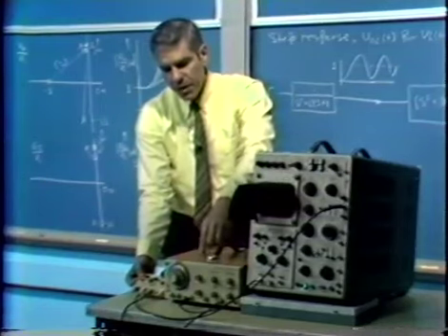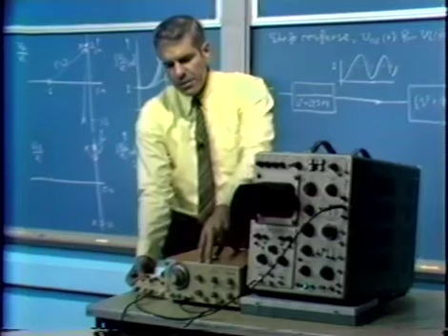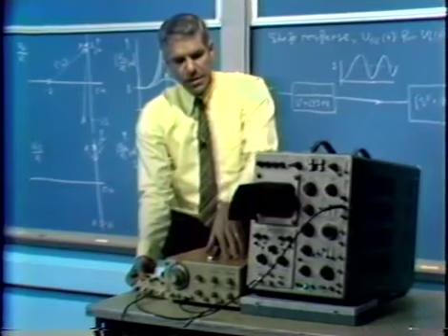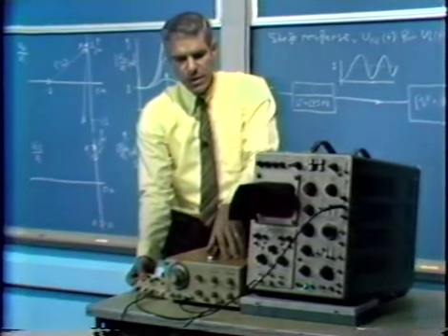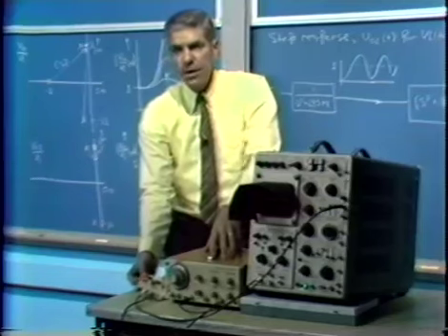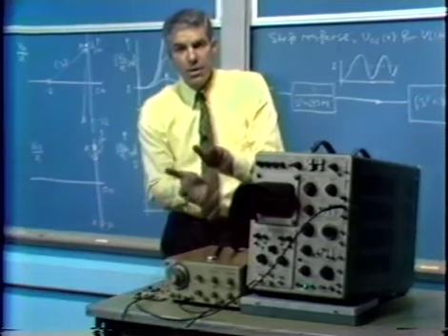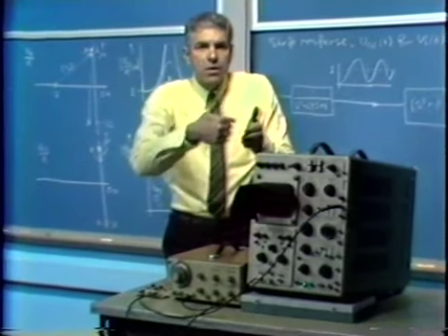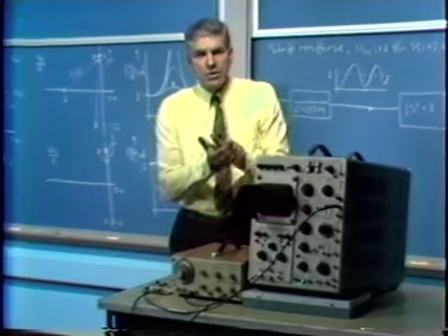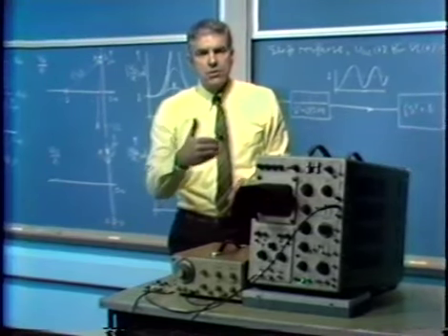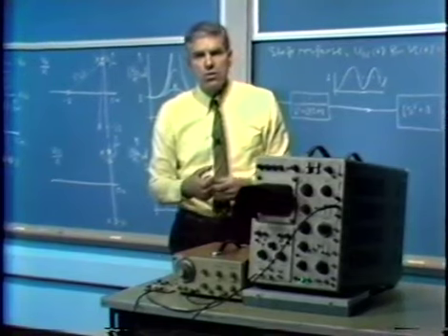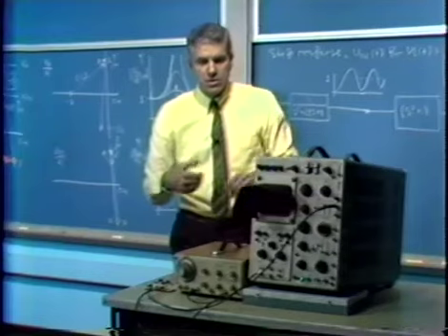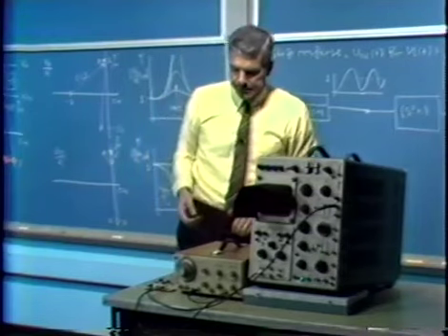For reasons of getting a clear presentation, it's easiest to do this with a sweep and without putting in the peak rectifier and all of that. So what we'll see in the oscilloscope presentation is simply an envelope that includes both the positive and negative portions. What's really happening is the carrier is running along inside this envelope, and we just see the outline of the envelope. We do a single sweep, which we store on a storage scope. The generator then retraces. So we'll look at single swept measurements of the frequency response.